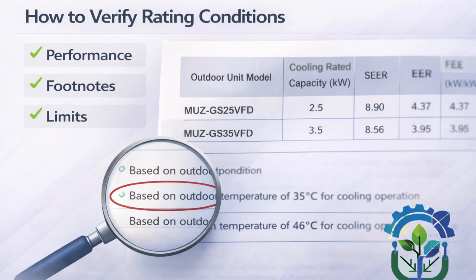Okay, and the power consumption. If this unit which has been proposed works at 1.6 kilowatt, it will consume more power to deliver the 1.1 or 1.2 ton at 46 degrees Celsius. And then third, the compressor load will get affected. At T1, the compressor is supposed to work at normal conditions, but now it will be overloaded at high ambient. What does this cause basically?